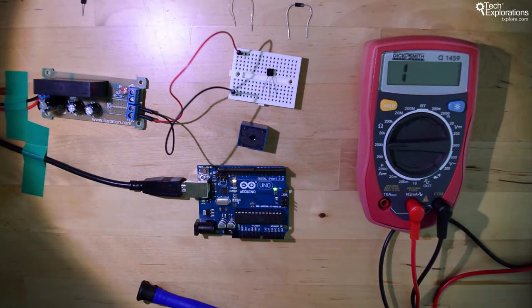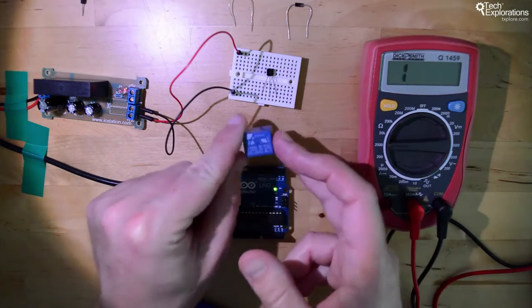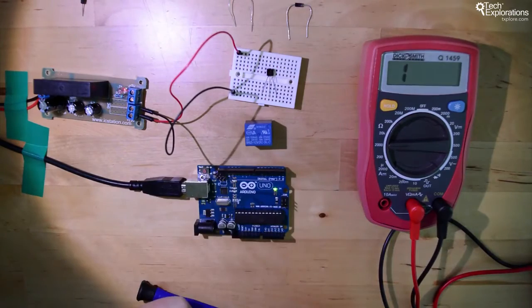The previous demo, obviously, in circuit was incorrect because it doesn't protect our Arduino from overdrawn current. And I want to fix that by coming back and creating an updated circuit, an improved circuit. In this circuit, we're going to use a 12-volt relay to drive the same 12-volt LED strip.